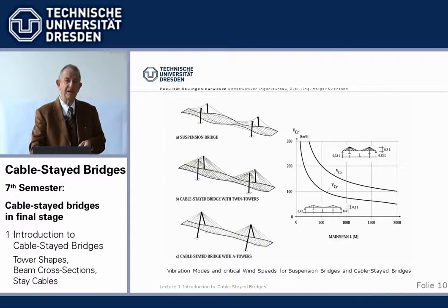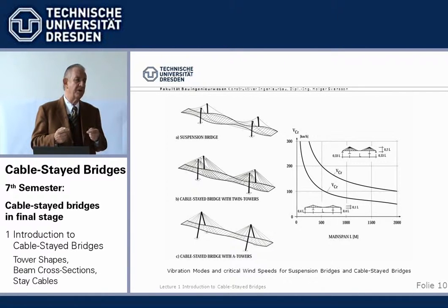So these are the advantages of cable-stayed bridges, in addition to a very economic use of material. Finally, that's the name of the game for practical engineers: we must find the least expensive design in order to win the competition to have our bridge built. And that has shown that in their span range, cable-stayed bridges are the most economic bridge system.